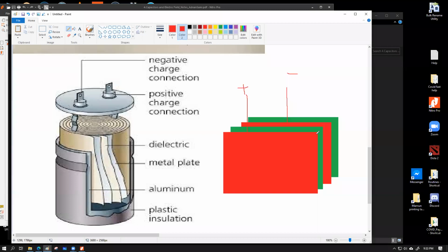And another benefit of having this kind of shape is that you do not essentially have to calibrate this whole thing. You can roll this out, and you can continuously measure how much capacitance this has, and whenever you get the expected value of capacitance, definitely within some tolerances, then you can cut this whole sandwich thing and roll it up and put it into your box, and you're done. So your production process does not have to be precise for every single component of your device.